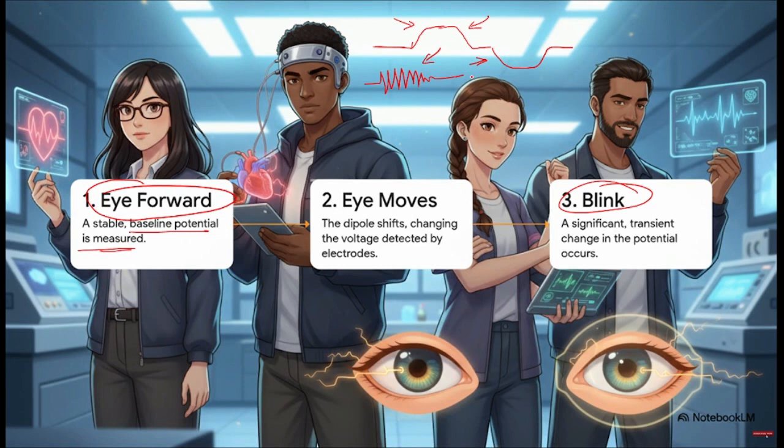It finds the envelope. After this pre-processing, you get a unique signal like this, and it will always be positive, because we square the signal first, so the negative portion also goes to the positive one.